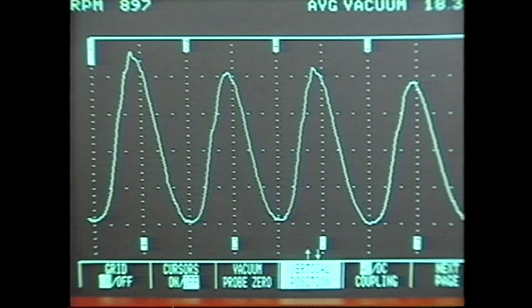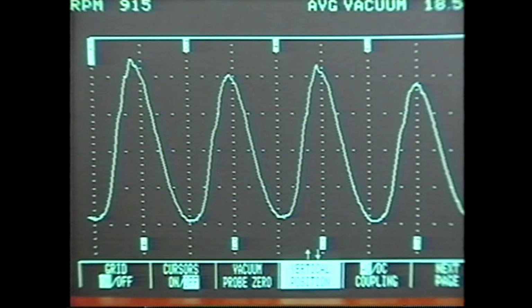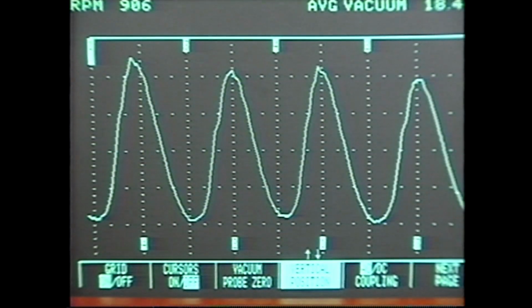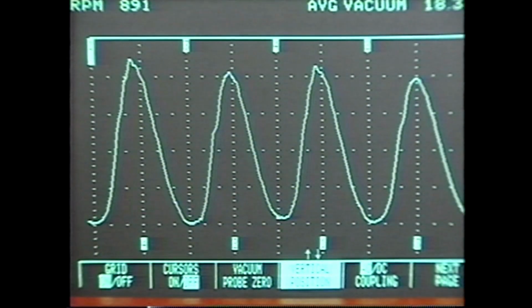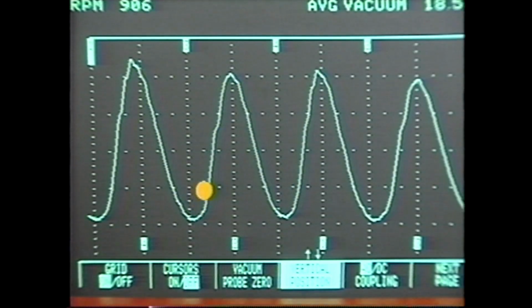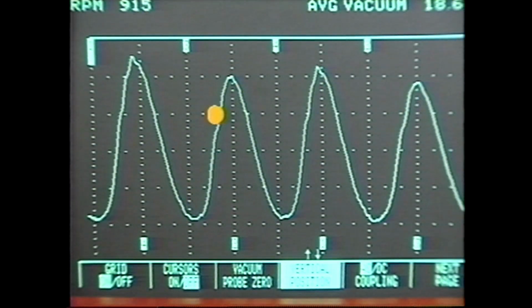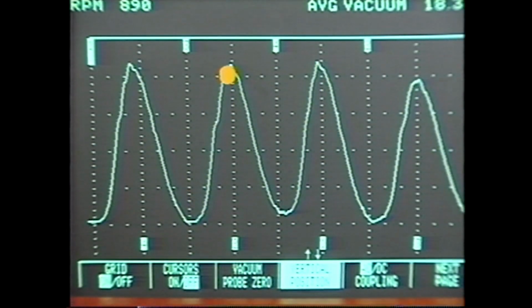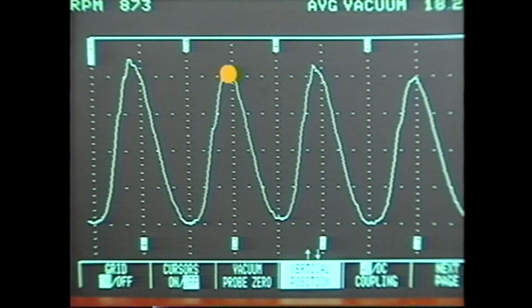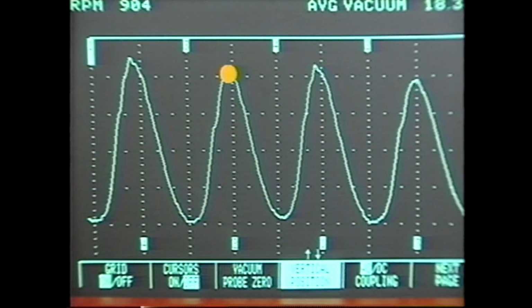The intake valve opens while the piston is still moving up on its exhaust stroke, pushing some exhaust pressure back into the intake manifold. This incoming pressure is displayed as a rising waveform. The exhaust valve closes, ending the rise. Note that the peak corresponds to a specific cylinder.